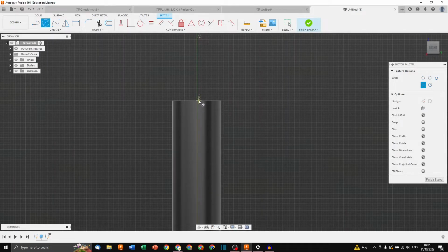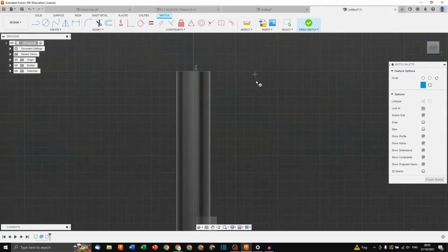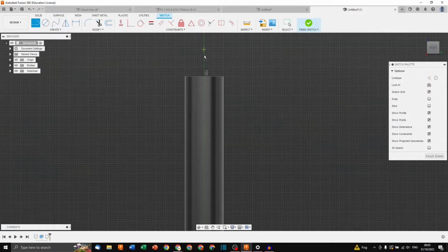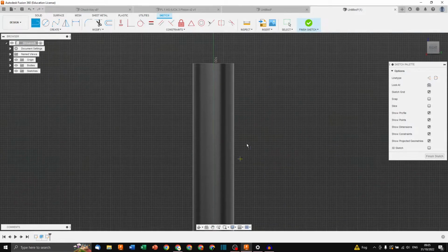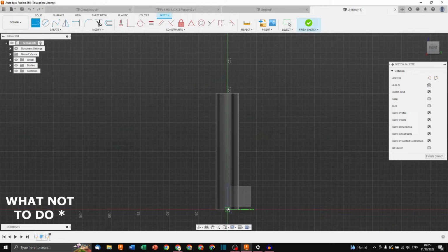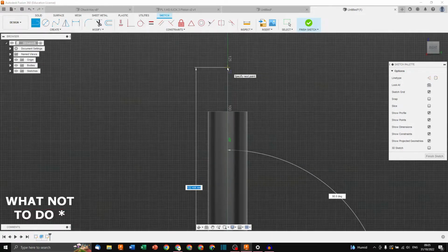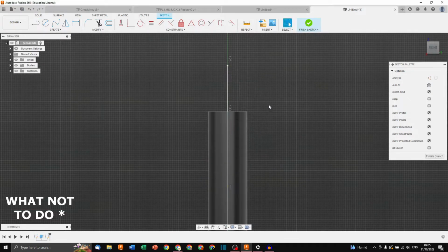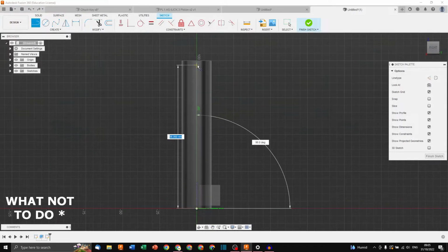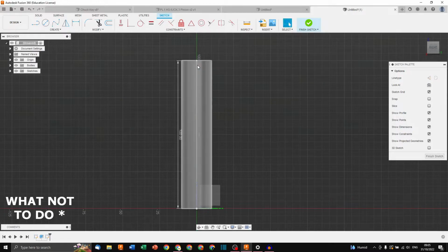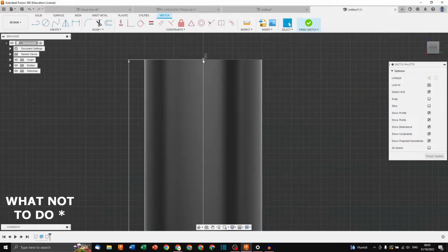Well, you know what? Look, it's not clipping. I could say, okay, well, that's fine. The green line is in the center of this tube. So I'll just go from the origin and then pull a line up and then stop it maybe here. Or you know what? No, I'll actually pull a line up, and since my handle is 100 millimeters, I'll enter 100 and I'm perfect. I found a point that now represents my handle.